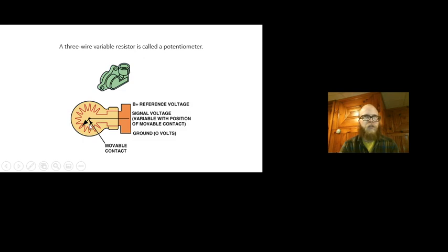These are most commonly connected to things like throttle position sensors, but almost every position sensor, aside from things like wheel speed and crankshaft, is a potentiometer. As the wiper moves across this, it picks up battery voltage, less than battery voltage, half of battery voltage, less than half, no more voltage. So 12, 10, 8, 6, 4, 2, nada.